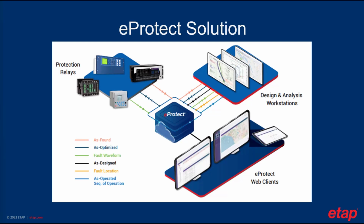From this, you can find your as optimized and as designed settings based off of your protection studies, and you can send those settings back to the protection relays. Additionally, fault waveforms can be downloaded from the protection relays and brought into the design and analysis workstations for calculations of your advanced fault analysis.